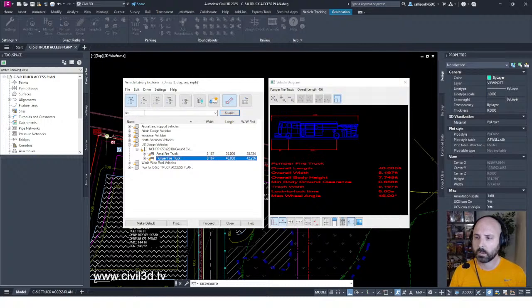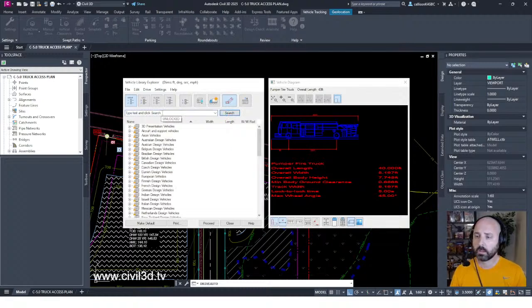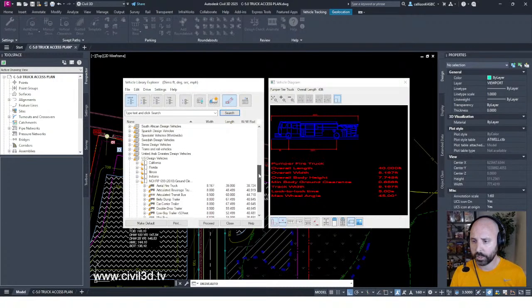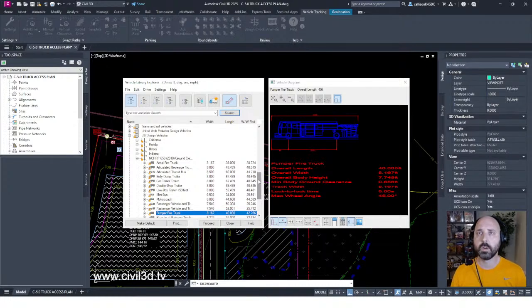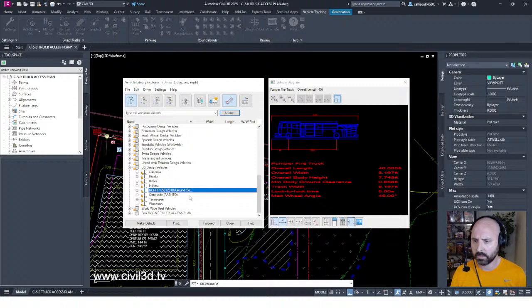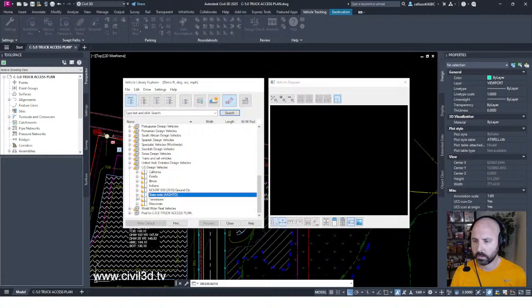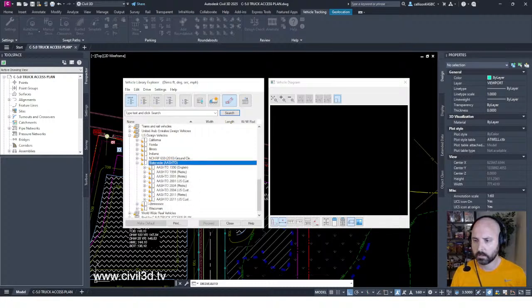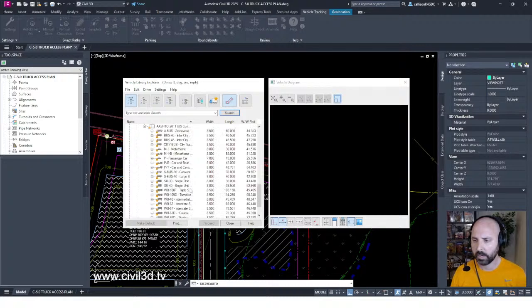So what I typically do is I'll ask the project manager, what's the size of the truck you'd like me to use for this vehicle turn? Or for this Autoturn? And I talked with my project manager, and he told me he wanted a WB 67, I believe. And if I minimize some of this stuff, we went with statewide AASHTO. Just expanded this. Expanded the latest and greatest here.